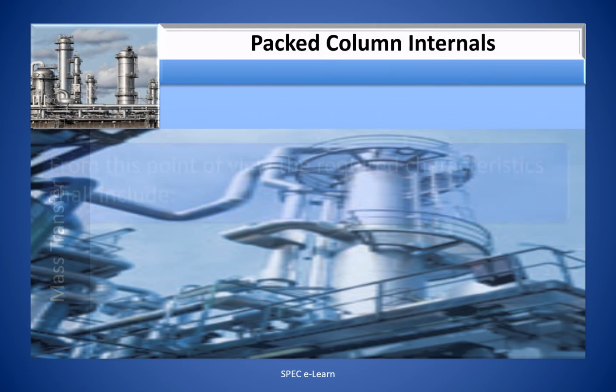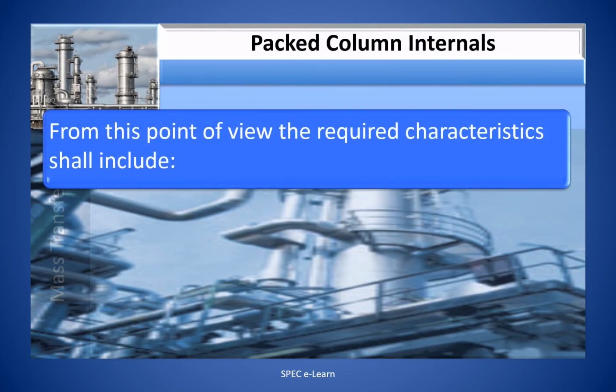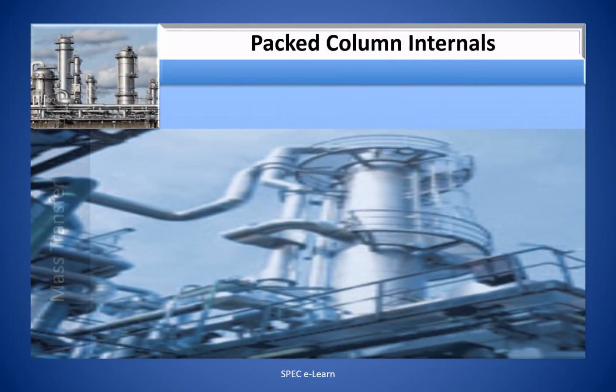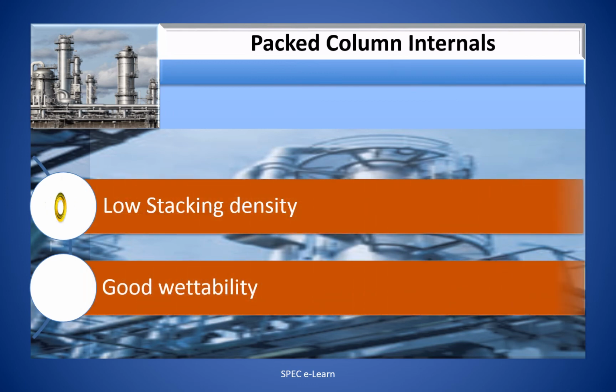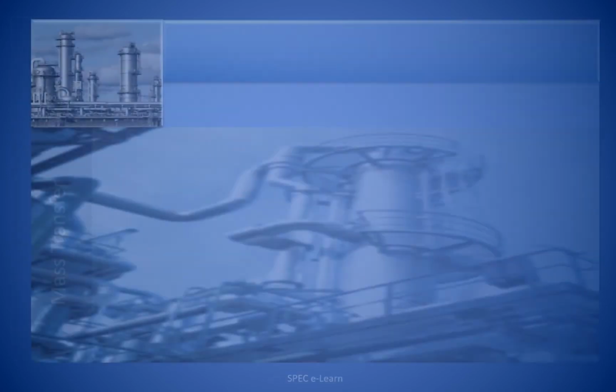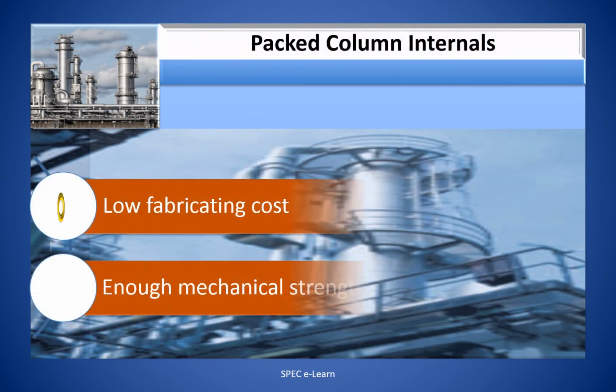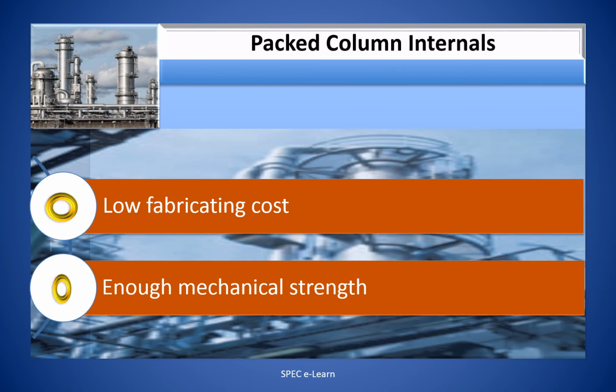From this point of view, the required characteristics of packing should include large surface area per unit volume of packing, large packing void fraction epsilon, low stacking density, good wettability, low fabrication cost, and enough mechanical strength.